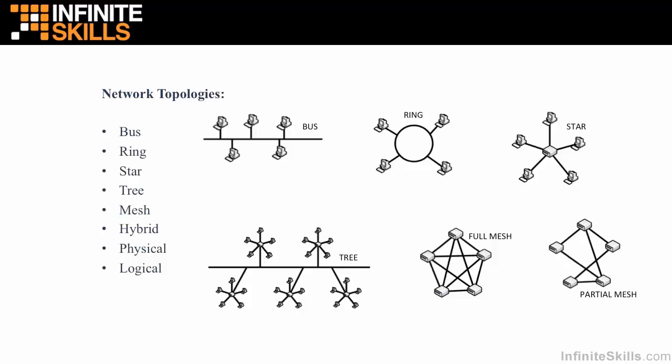However, in time, these connector blocks became powered and were amplifiers or repeaters, if you will. In a digital sense, we would call that a repeater. So in addition to it having all the right connections so that different nodes could communicate amongst one another, that central point that required power was also a repeater that would regenerate the signal.